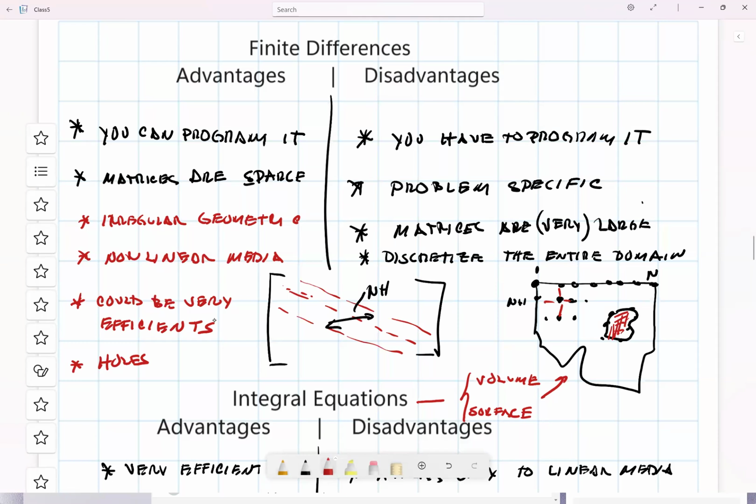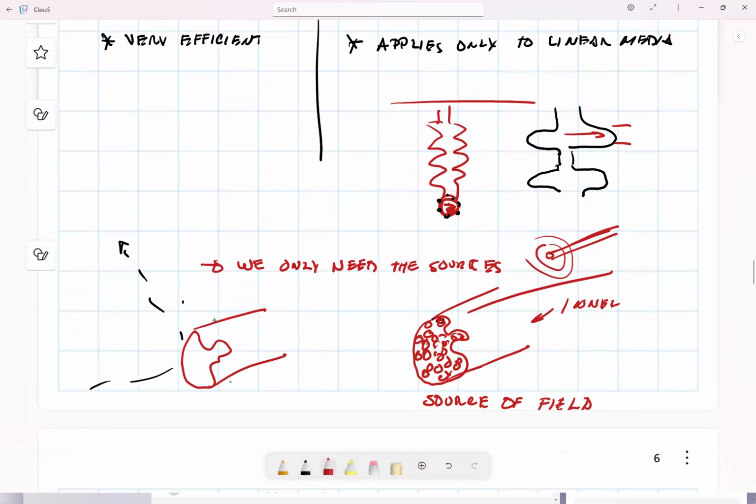So you still need to do something with the time when you have time domain. So you need to solve the transient. You will have to get an integration method for the transient, right? I am not sure what Comsol does, but you can use any of the existing integration methods. You can use Euler, forward Euler, backward Euler, trapezoidal rule of integration or any of the Runge-Kutta methods. I don't know which ones are programmed in Comsol. Okay. Thank you.